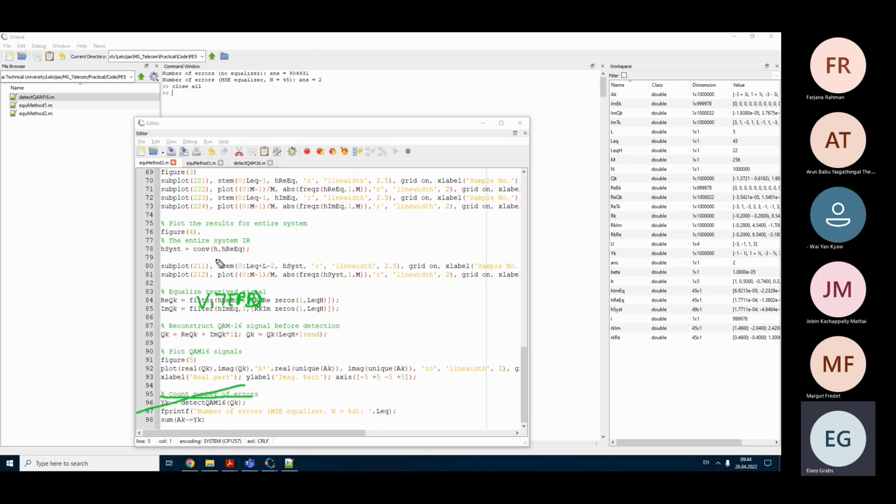So it is a detector that can be used as a demodulator. At the same time, it also works as an equalizer since it is trained for some particular impulse response. So this Viterbi detector will be for a specific impulse response just the same way as any equalizer.